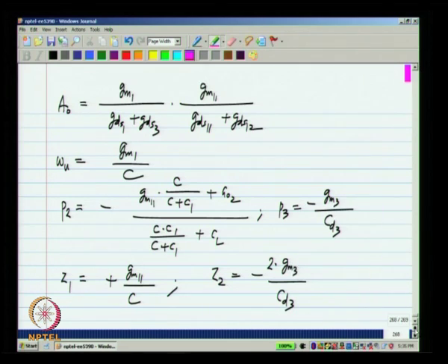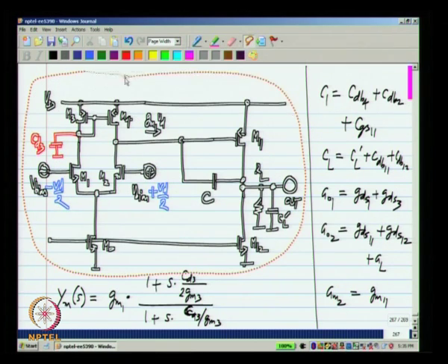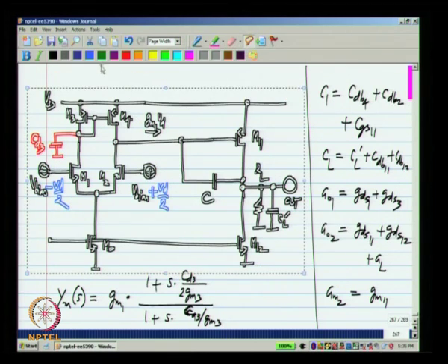Now, these summarize the small signal DC and AC performance of the op amp, and we have a higher DC gain and we have a number of parasitic poles, and we know what to do with them. We have to place them sufficiently beyond the unity loop gain frequency of whatever feedback loop we operate that in. Now, let us evaluate some other relevant parameters of this op amp, like the noise, offset, slew rate and the swing. Okay.